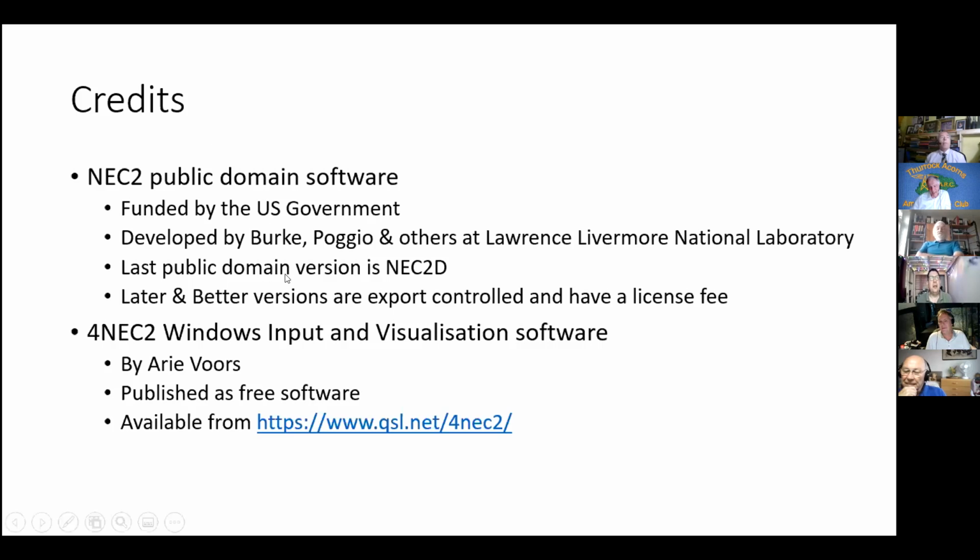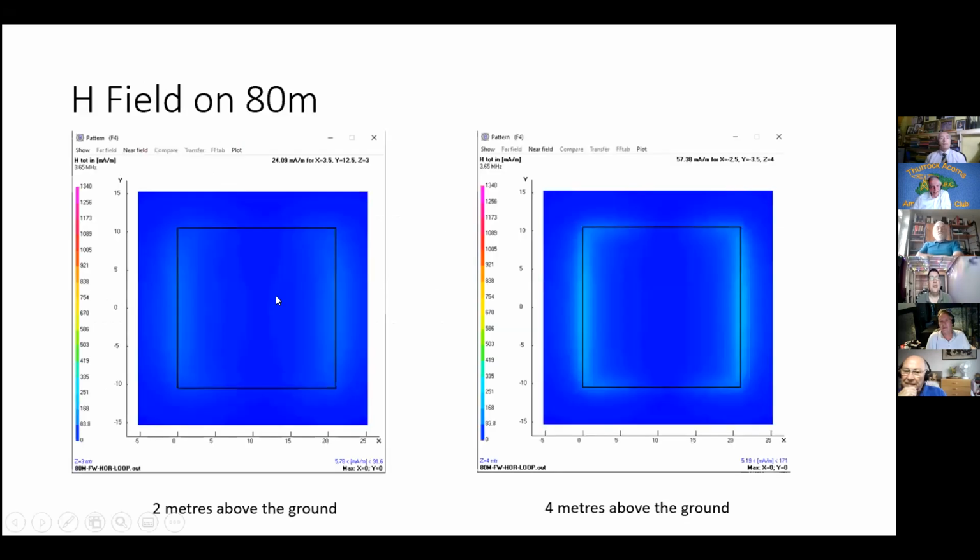Has it got to be a quarter wave on each side, or can you do like 3/8 down two of the sides and then shorter ones on the others? It will affect the radiation pattern, but it won't affect the resonance unless it's ridiculously short. My friend's one is probably about twice as long as it is wide.